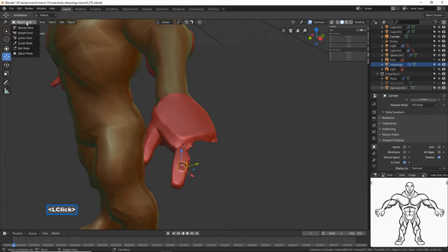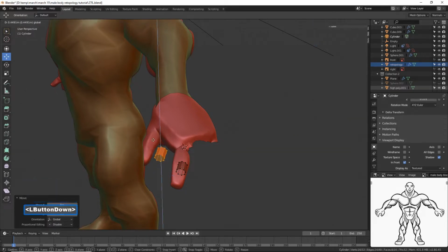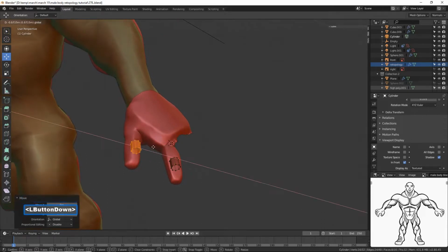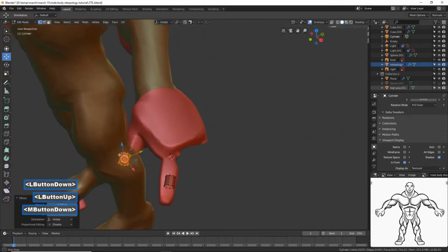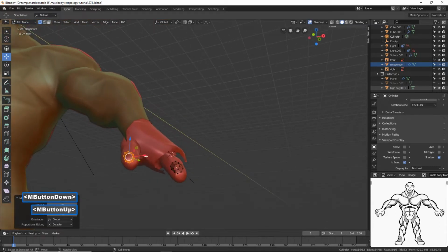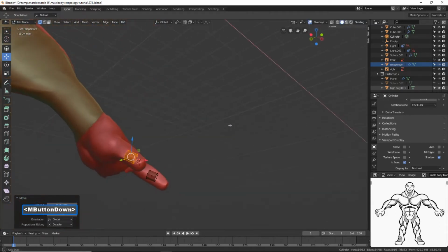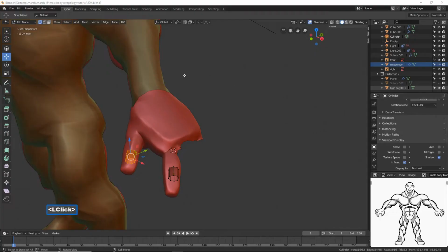With this selected, we're going to go to edit mode. We'll hold Shift, press D, right click. We just duplicated the cylinder by right clicking. And I'm rotating in 3D space to see this going in the thumb. It looks like that's in the thumb, which is good. Okay, I'm going to left click to deselect. I'm going to go to the upper left, click to go to object mode.